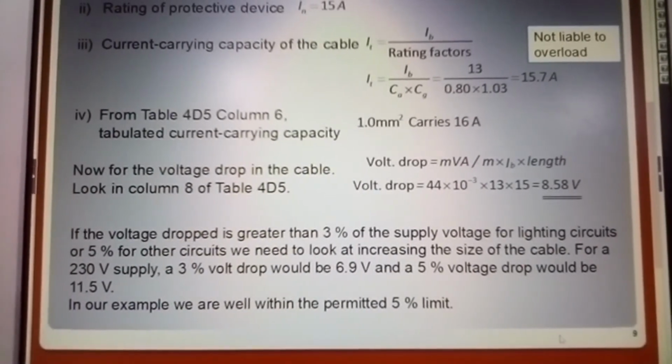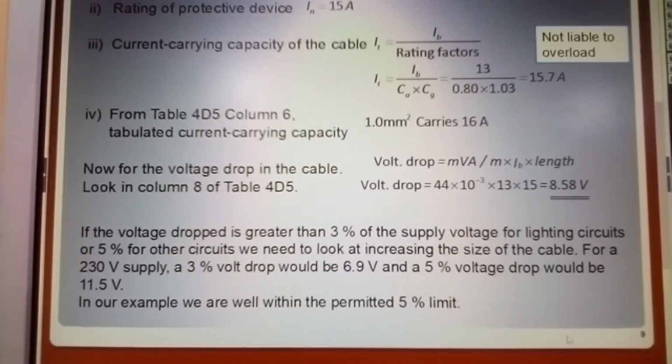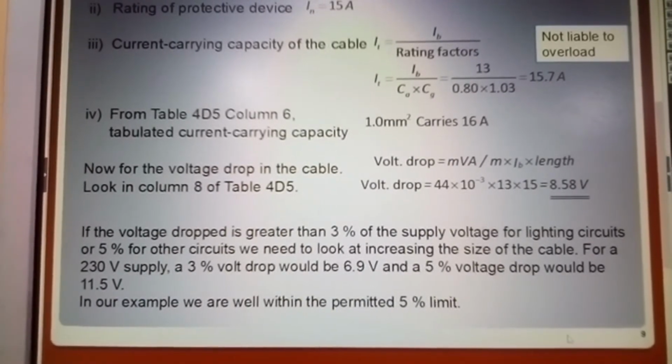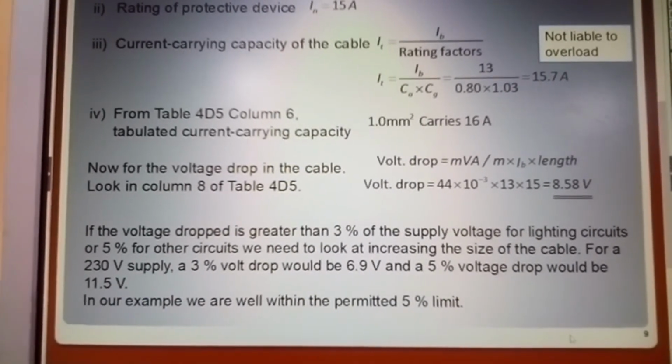And again, confirm that we are allowed 5% voltage drop for lighting circuits.